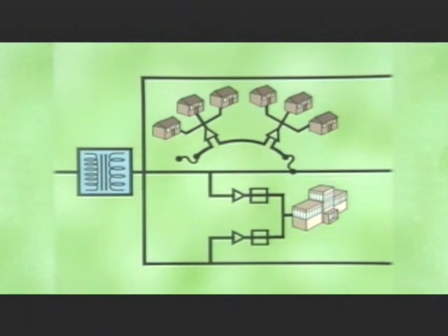Between the bus and each transformer is a protective relay. Under normal circumstances, both relays are closed. The secondary bus is then supplied with electricity from both feeders. However, if a problem develops, for example, with this feeder, this relay will open automatically. The bus is now being supplied from the feeder connected to this transformer. Even when there is a problem with the system, the hospital will experience no loss in service.